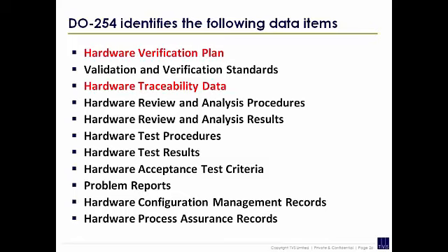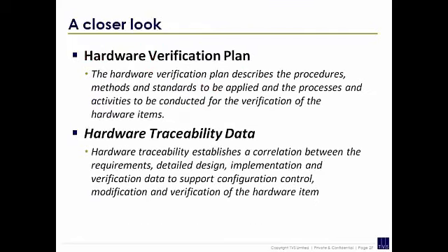requirements. Okay. So a closer look: the hardware verification plan describes the procedures, methods, and standards to be applied, the processes and the activities conducted for the verification of the hardware item. Traceability data establishes a correlation between the requirements, detailed design implementation, and verification data to support configuration control, modification, and verification of the hardware item.